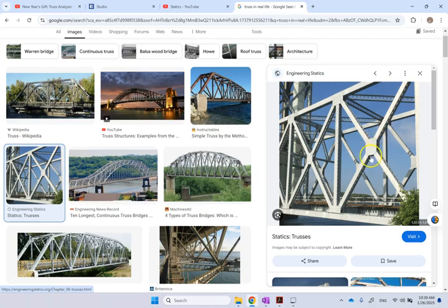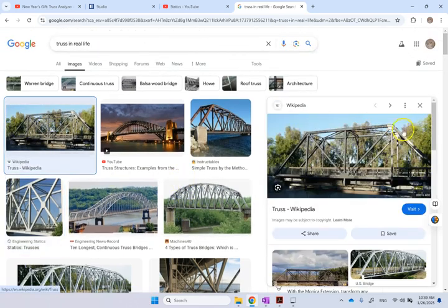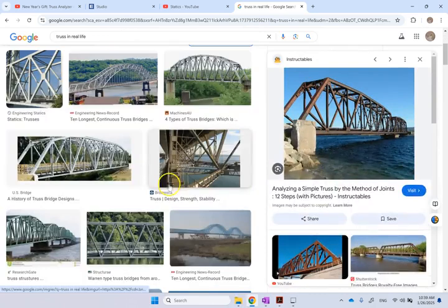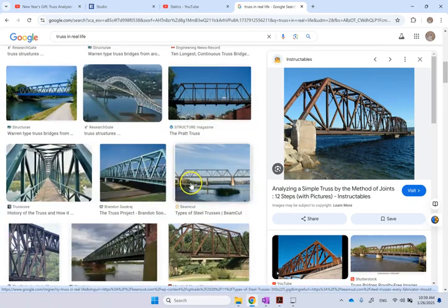Or they could be bolts, or sometimes there could be welding. In older ones, sometimes they use welds, but most of the time they use rivets, which are much better in terms of strength against earthquake and shaking, because welds are very susceptible to it.